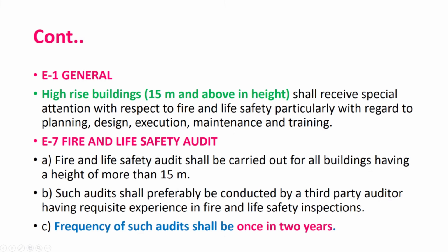So it should be clearly mentioned, in case you want to make that particular FOB fit for 2-wheelers or for that matter 3-wheelers, then that factor will be required to be taken care of while designing. That's why this correction slip has come in 2022 itself. Design of a foot over bridge should provide for covering, which should preferably be provided at the initial stage itself.